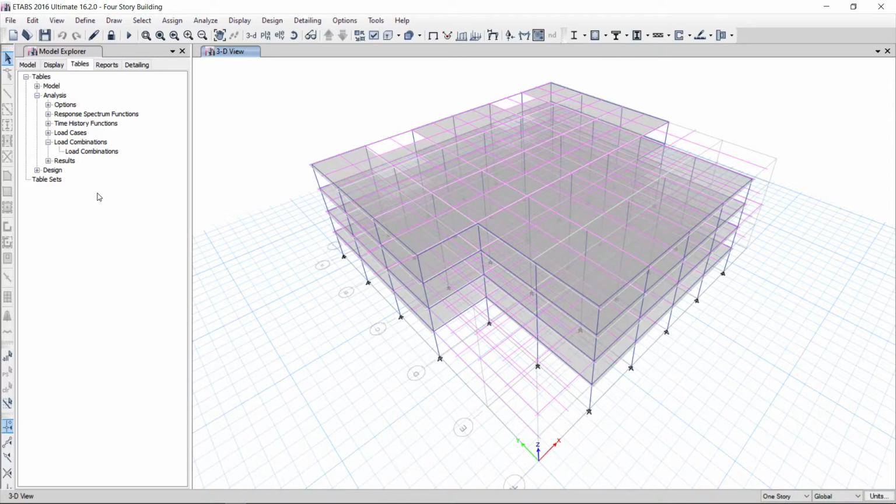Don't take 100%, when on the structure, in case of an earthquake, there will not be 100% live load. That means they have ignored a very essential combination, and because of that, in case of a higher seismic zone, my structure will be a bit uneconomical.